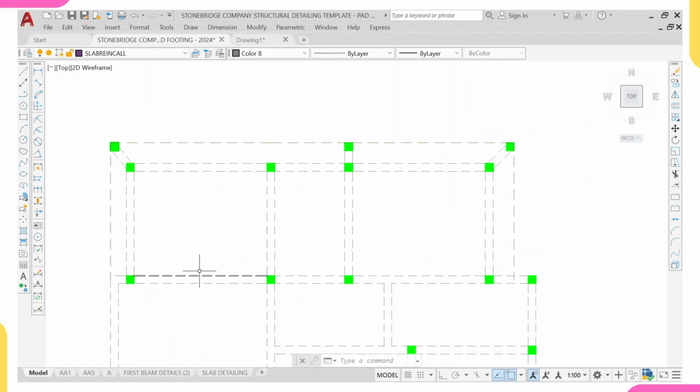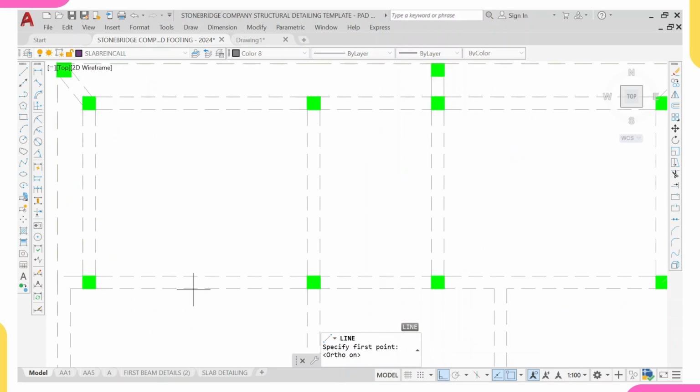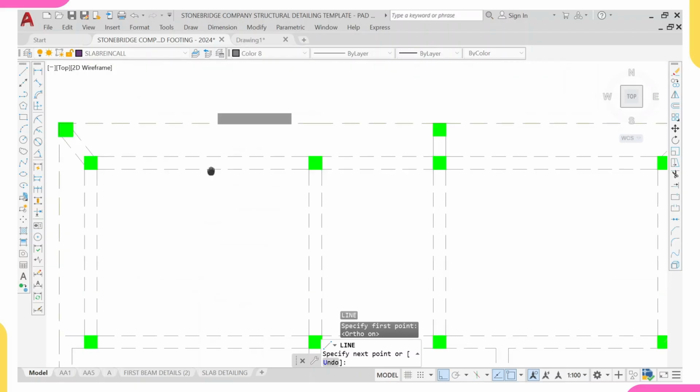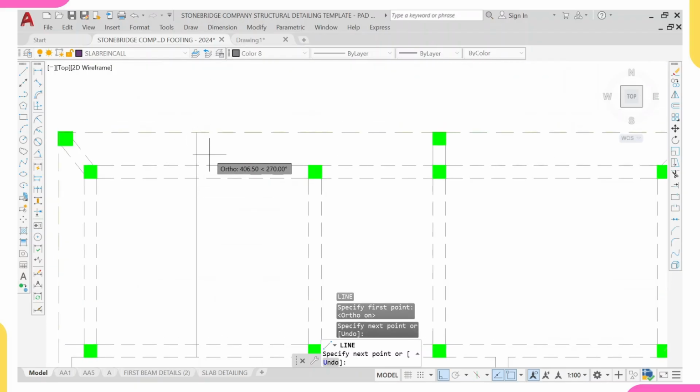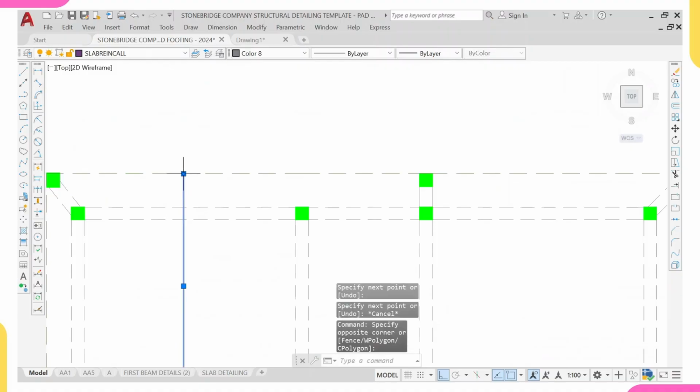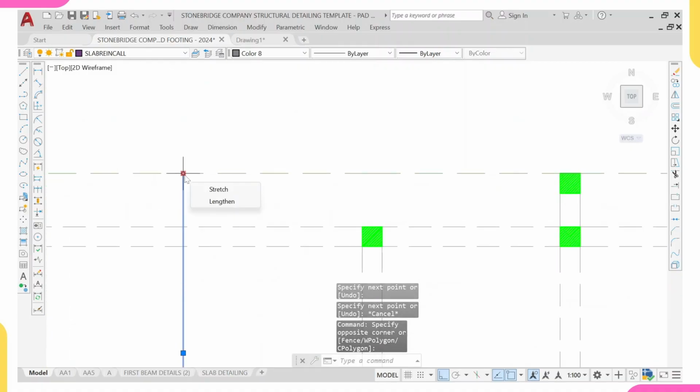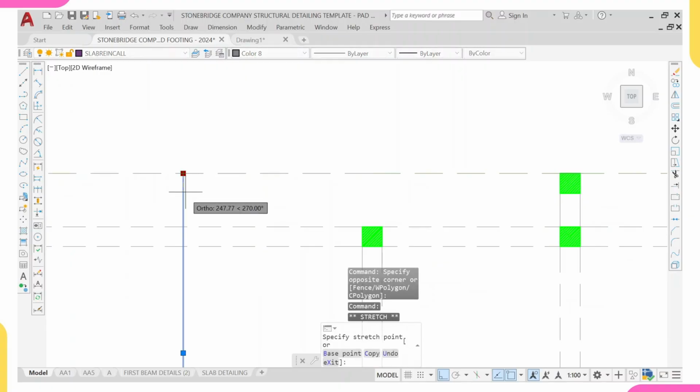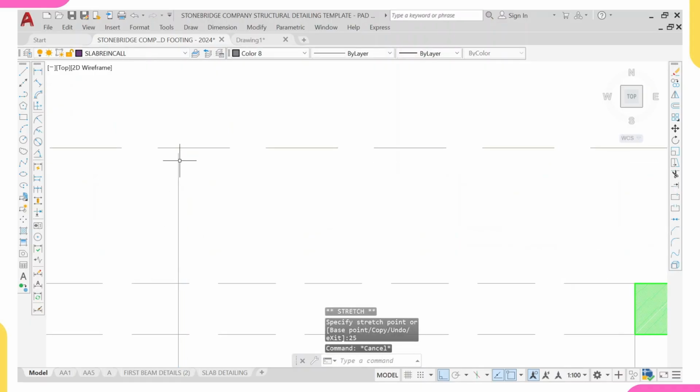So I want my first reinforcement, L, enter. I will turn on my auto key by pressing Control F8. Yeah, so my auto key is turned on. I want my first reinforcement to run from this point to this point. But if you can remember, our concrete cover is 25. So I'll offset 25 backward. I'll click on it, do 25, draw it backward, and press enter. So if you can see, I've offset 25.